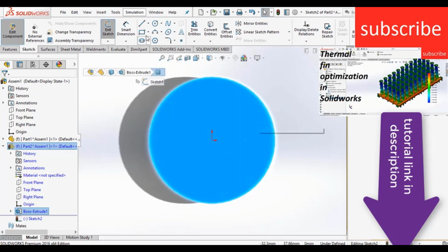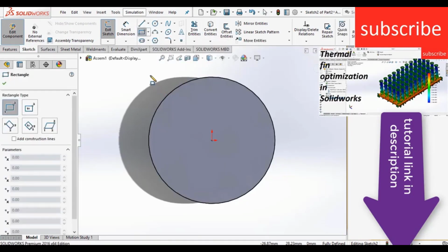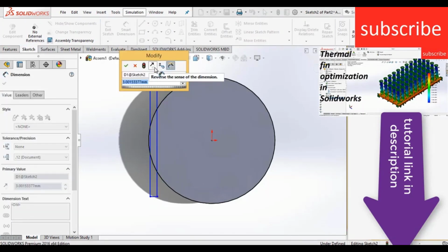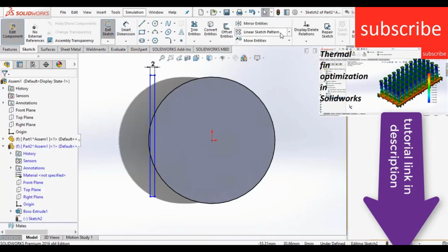After that, select the edge and click on convert entities. Now draw a rectangle and give it a thickness as per the requirement. Here I am giving a thickness of 2 mm, and go to linear pattern.